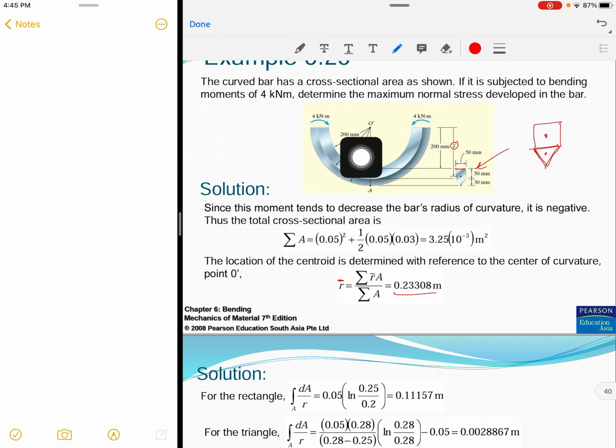From the geometry of the bar, we need to find r over h and w over h. R is the radius of the fillet, h is the width of the small area, and w is the bigger width. So 0.2 and 1.5. By using these values, you can get the value of K. 1.5 is this curve, and 0.2, we connect with the 0.2 right there, and then you can approximate the value, which is 1.45 if I'm not mistaken. Yes, it is accurate, 1.45.